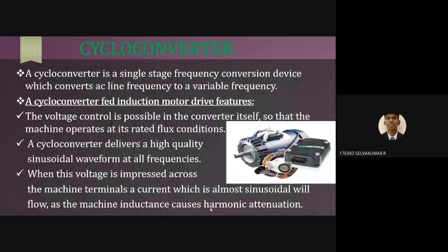Next, the cycloconverter. A cycloconverter is a single stage frequency conversion device which converts AC line frequency to a variable frequency. A cycloconverter feeding three-phase induction motor drive has the following features. Voltage control is possible in the converter itself, so the machine operates at its rated flux condition.